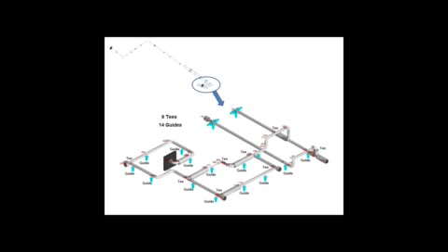If we go to the next slide, when we see something like this, we say, wow, that's pretty flexible. But whenever you see a whole lot of pipe, what you have to do is look for local flexibilities. So if we zoom in on the bottom part of that, what you'll see is that somebody put in a ton of supports here for some reason. They put the supports in and forgot that the support spec that he was using had guides on every support. So everything was over-restrained and, well, this system was overstressed artificially.